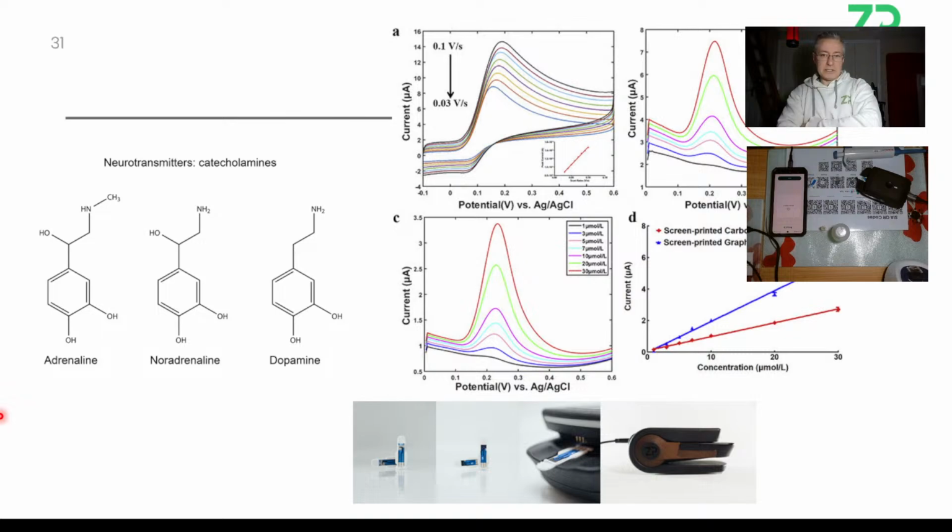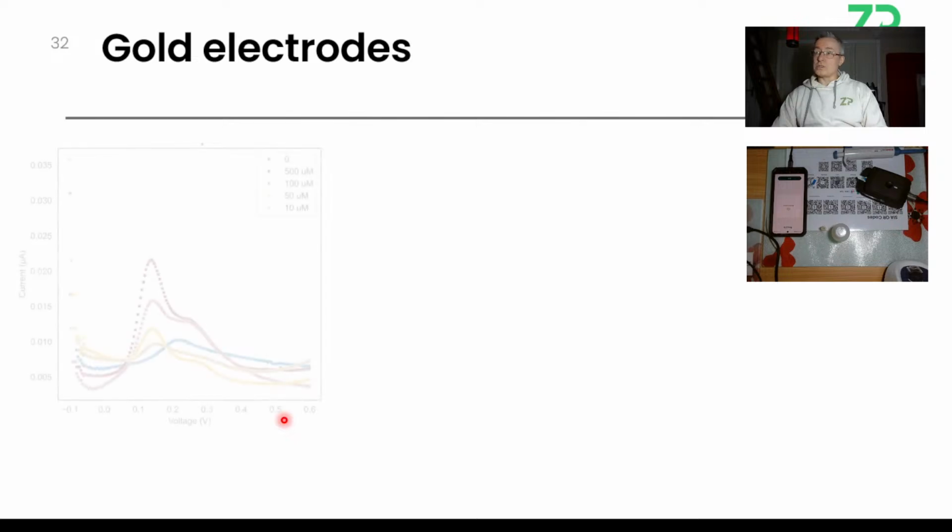Whereas gold as a material is 24,000 times more expensive than carbon. So it's never going to make for a low-cost sensor. Now in this particular application, the sensor might not need to be low cost, but personally, especially in the lab and R&D, when budgets are limited, carbon's probably a better material. They didn't particularly need gold.